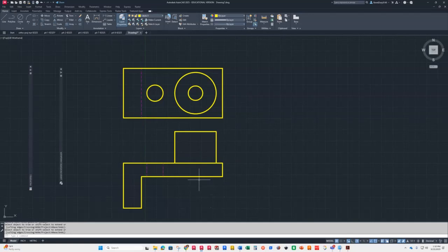Okay. Now this hole goes all the way through. If you don't see a note that gives it a little depth, you assume it goes all the way through. Yes, sir. What line did you offset just now? The top of the L right here. Oh, I see it. And then you offset it 35. Yep, it goes up 35. That gives you the top of the boss.